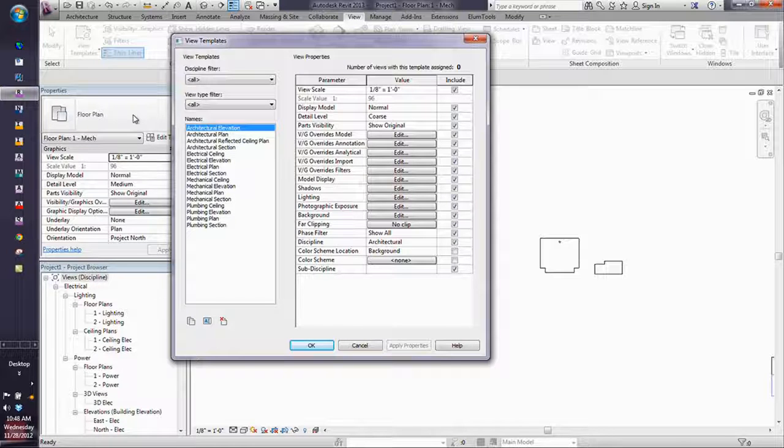So I'll tell you a way that I cheated in here. I actually took their model into AutoCAD. Yes, I really did this. And then I used a tool in AutoCAD MEP called Create HLR. Has anybody ever heard of that? It's a little command that takes a 2D picture of what you see. The region command also does this in AutoCAD. So what I did was I took that and I used it to make just a 2D outline of what I saw in an elevation and in a plan.